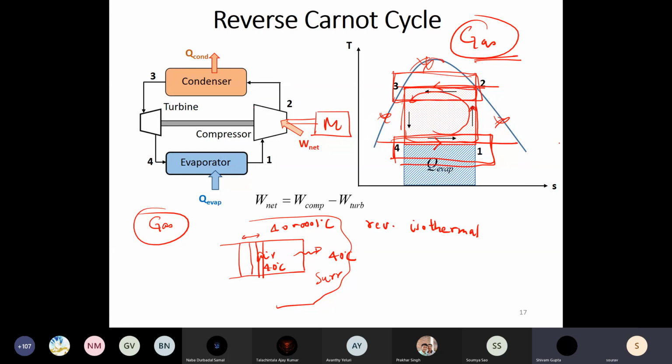Okay. So again, I am telling you, please do forget about the liquid vapor line. We'll come to the vapor cycle a little bit later. So this is what you would have studied in your +2, and in your UG classes also. So you will always assume that the working fluid is trapped within the piston cylinder assembly. This is the isentropic compression, isothermal heat transfer, then isentropic expansion, and then again heat transfer.